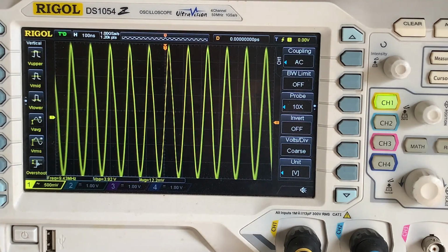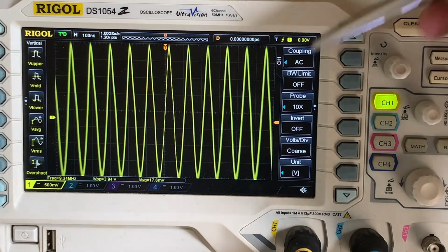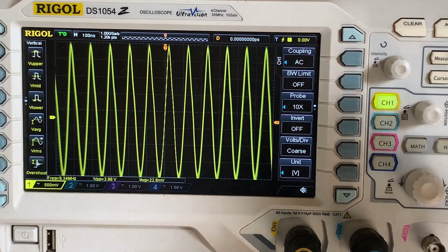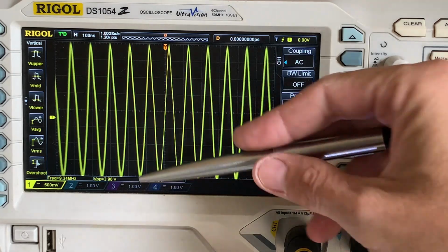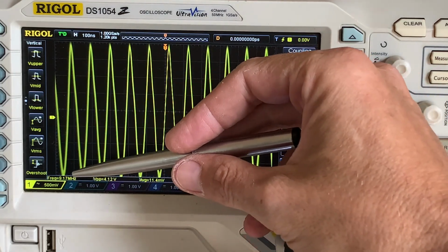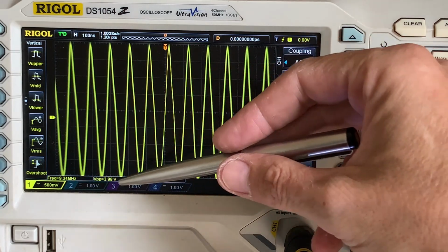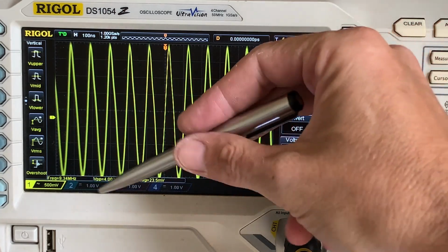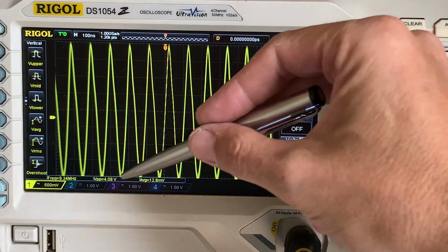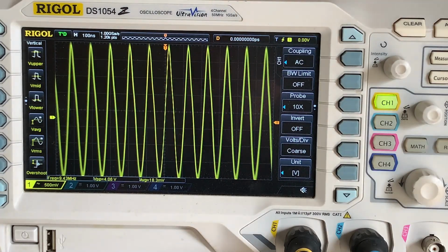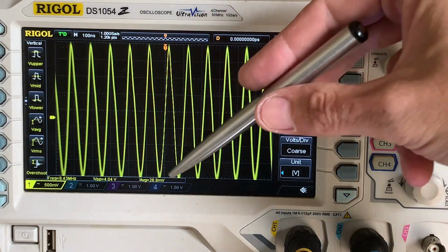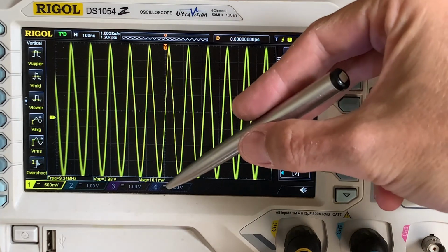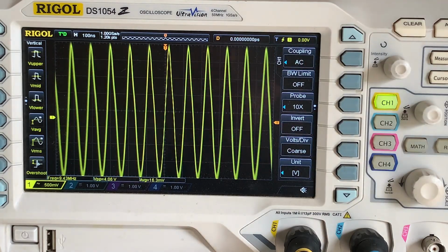Of course, the signal is AC coupled because I want to see what AC noise we're getting, and we can see it's at a frequency of 9.5 megahertz. Voltage peak to peak, in other words from there to there, is roughly about 4.1 volts of noise. Although, like I said, the average voltage of that is only 20 millivolts, and that we of course want to get rid of.